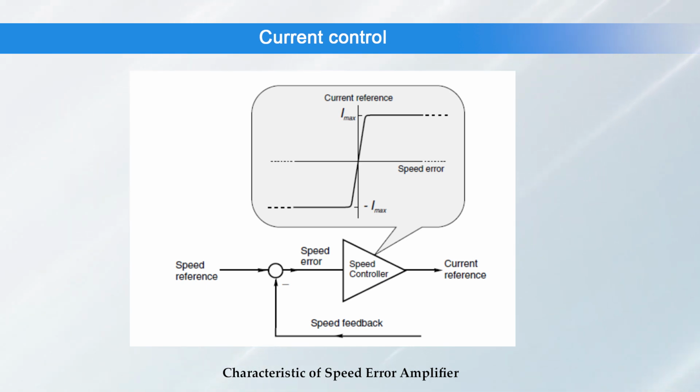It is important to avoid having too much current in the converter, and we have already talked about this. The current control loop helps to prevent this from happening. As long as the current control loop functions properly, the motor current can never exceed the reference value. Hence, by limiting the magnitude of the current reference signal by means of, say, a clamping circuit, the motor current can never exceed the specified value which is shown.